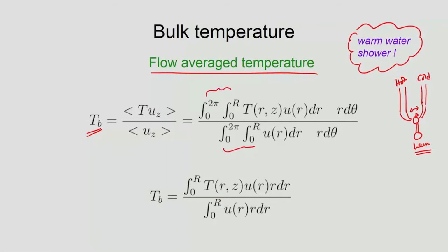Now, the bulk temperature actually means that whenever you have the temperature varying as a function of r and z, we do not want to put thermocouples and measure the temperature. So, what we do is that at any point at any z, if you were to take that liquid out into a container and let it mix and then ask what is the temperature of that mixture, that would be the bulk temperature basically. This concept is very useful to know what would be the effective temperature that is coming out, and the way we evaluate it is written here.